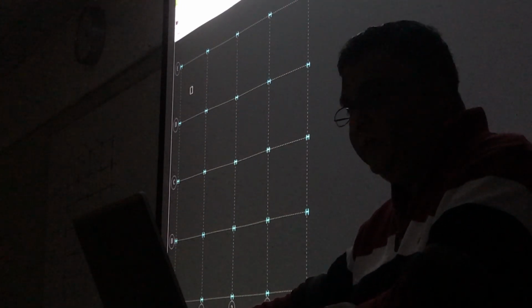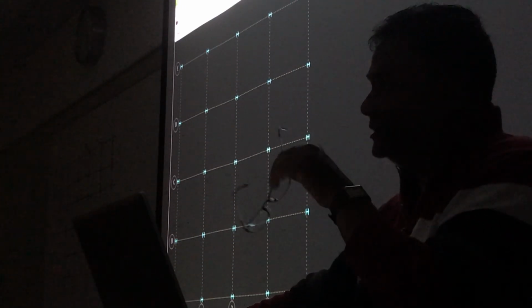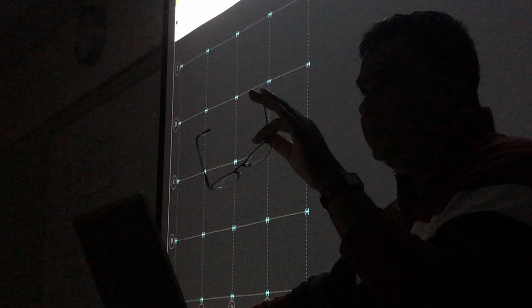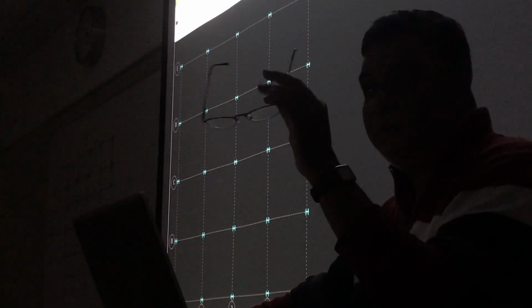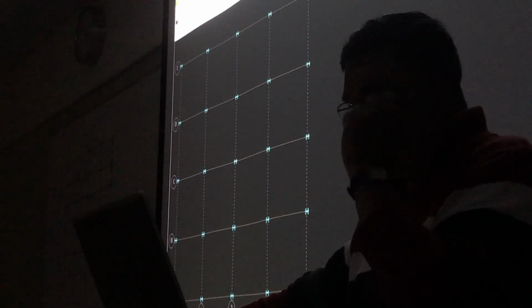Okay, so we are showing the columns, but not done properly. We will have to change some of them. Now, after the column, we will get the beams, and if you see the major ones, the girder ones are connected between columns and columns. So we connect them first. So add on grids, and again I will say that my first beams are gravity beams, composite.